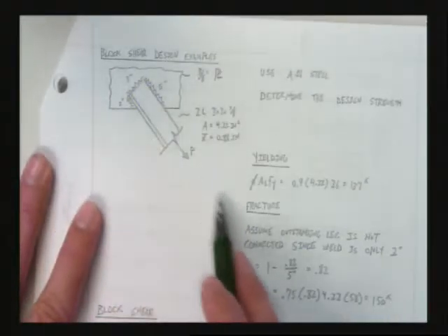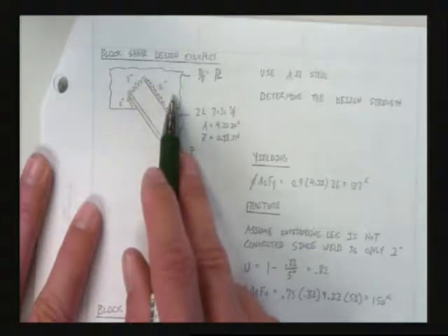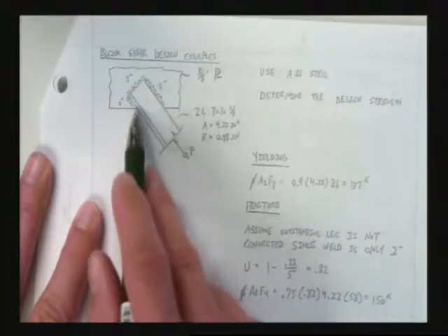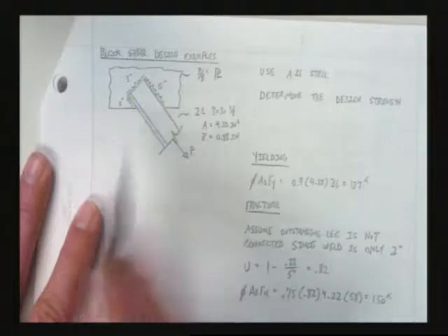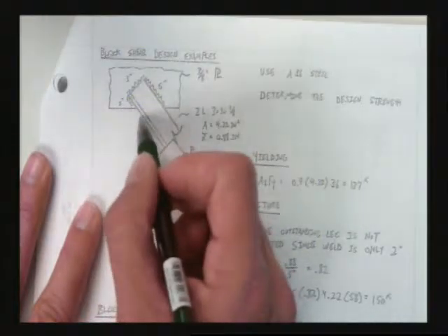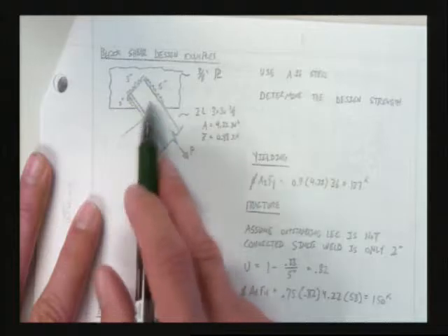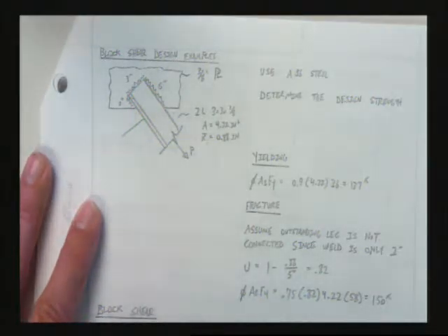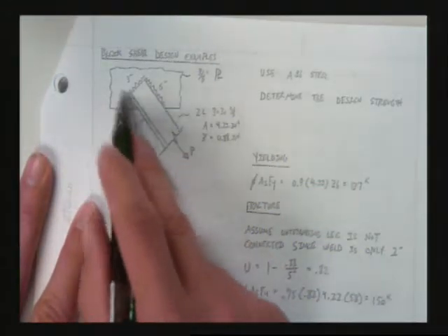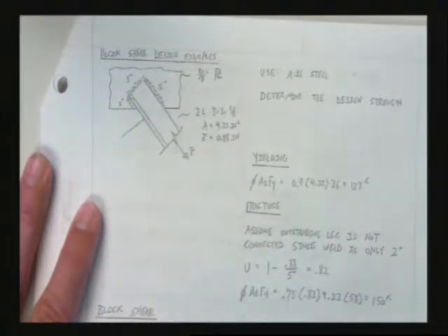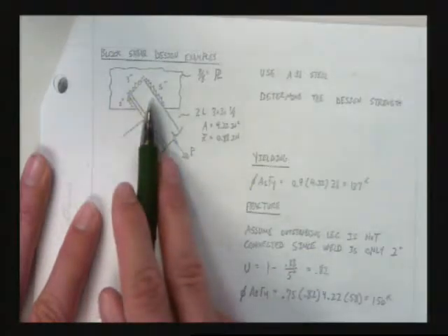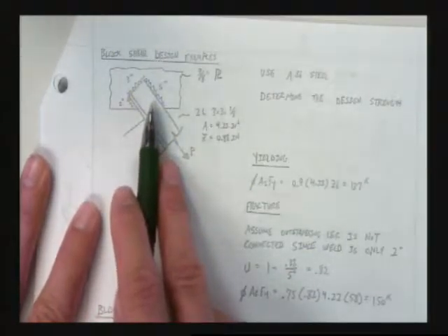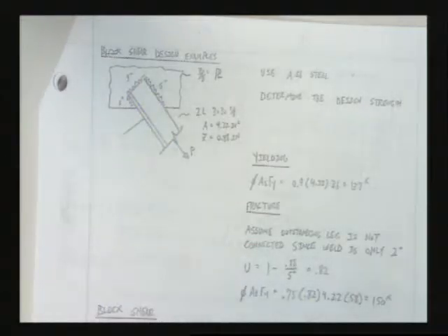You have a diagonal that comes into a gusset plate, okay? Because of the geometry of the situation, you don't want to make a funny looking gusset plate just so you can have an equal leg weld on both sides, right? We're going to save some steel. We're going to cut this gusset plate back. Very, very common. When it comes to the welds, they want to weld around the outside, right? They're going to weld it all down. They're going to want to know how strong it is, how thick it needs to be. So how do you handle a problem like this?